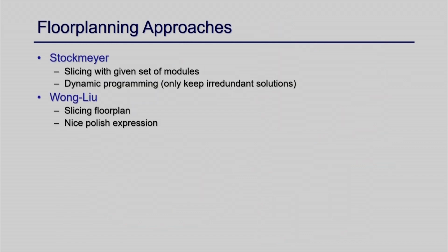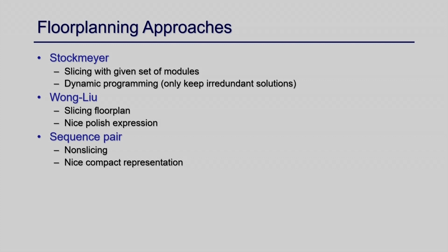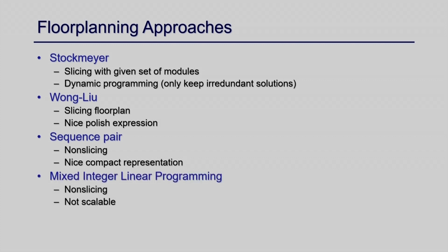Again, this floor planning, you understand there are a lot of approaches, and because this is an NP-complete problem, an optimal solution cannot be obtained by some optimal algorithm. So various kinds of heuristic approaches are also available for this step as well. Okay. So I move on to the next step, which is placement.